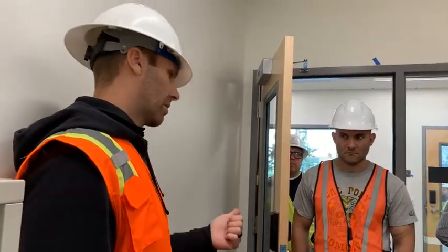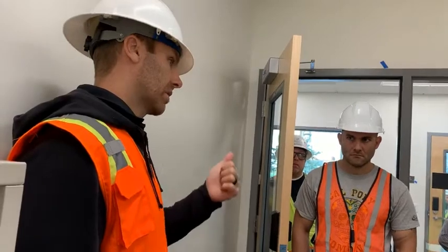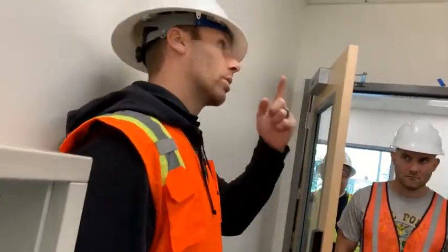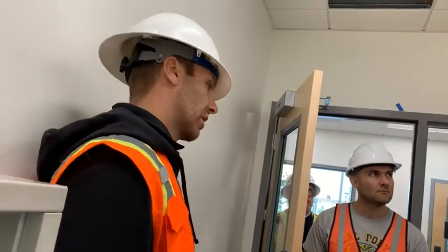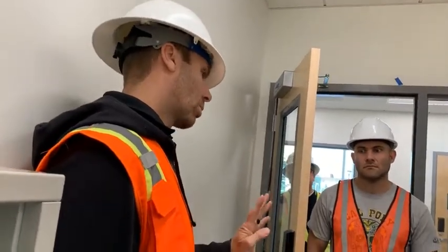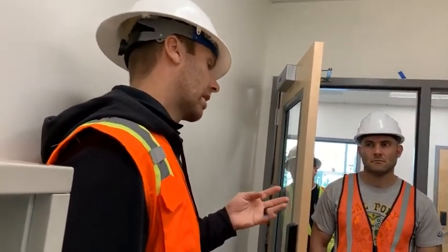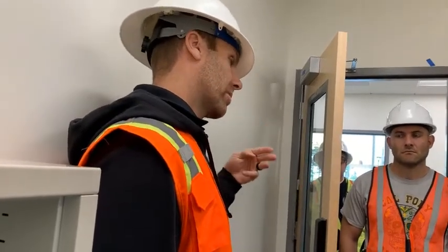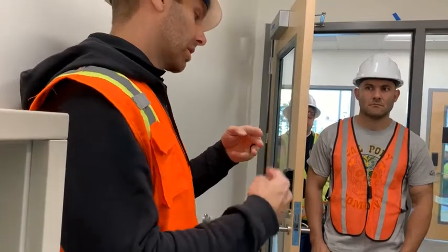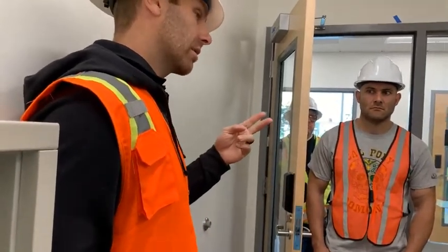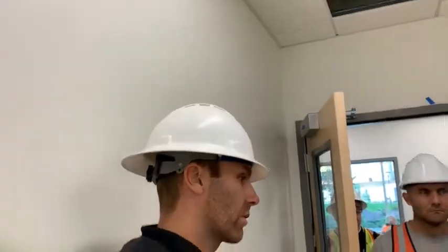It's going to be generated off the relay you're using if it's a lighting relay, or if you have an intelligent fixture, it's coming off that intelligent fixture. So if you open one of these fixtures, you'll actually see 4 wires going, well, you have a ground, so you have 3 other wires going from the driver to what's called the NIO, where the Cat 5 is plugged in. Purple, gray for your 0 to 10, and then blue, 24 volts.